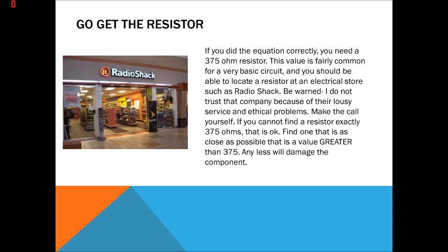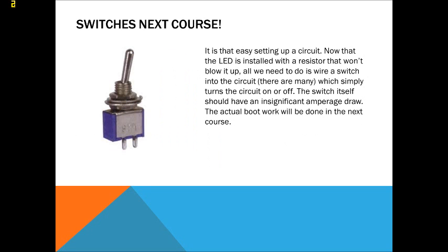Make the call yourself. If you cannot find a resistor of exactly 375 ohms, that is okay. Find one that is as close as possible that is a value greater than 375. Any less will damage the component. It is that easy setting up the circuit.